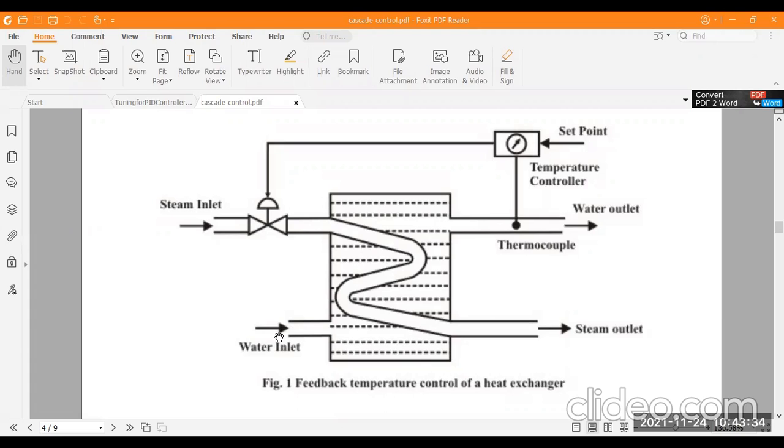Another one is the water inlet, where we apply normal or cold water into the chamber. Using the steam line, the water is also heated, and we set the temperatures. These are basically controlled by the temperature set point. This is one set point where the user or the automatic control system sets the particular desired temperature value, and this temperature is maintained by the temperature controller.